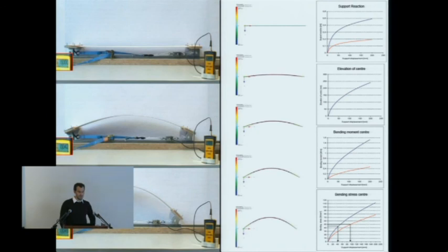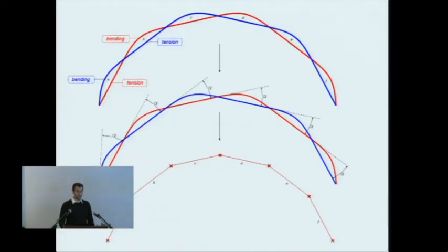So this project, as all projects, began with physical tests, in this case of the bending deformation of thin birch plywood strips and related finite element simulations. Based on these physical as well as computational tests, the bending behavior of the material was investigated and developed towards a basic structure that employs the bending behavior in local segments rather than the overall arc.